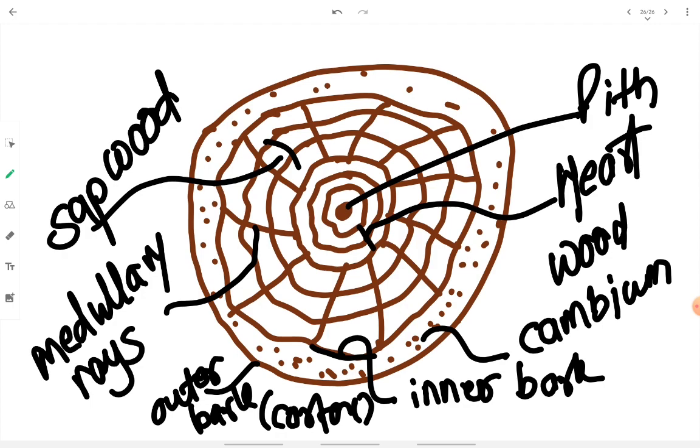I think that was enough for the initial part. In this part we saw the types of wood: coniferous, deciduous, hardwood, softwood. Then we saw annual rings, medullary rays, what is pith, what is cambium, what is inner bark, what is outer bark, that is cortex, what is sapwood, what is sap, then desired properties such as tension, compression, bending stresses, and modulus of elasticity.